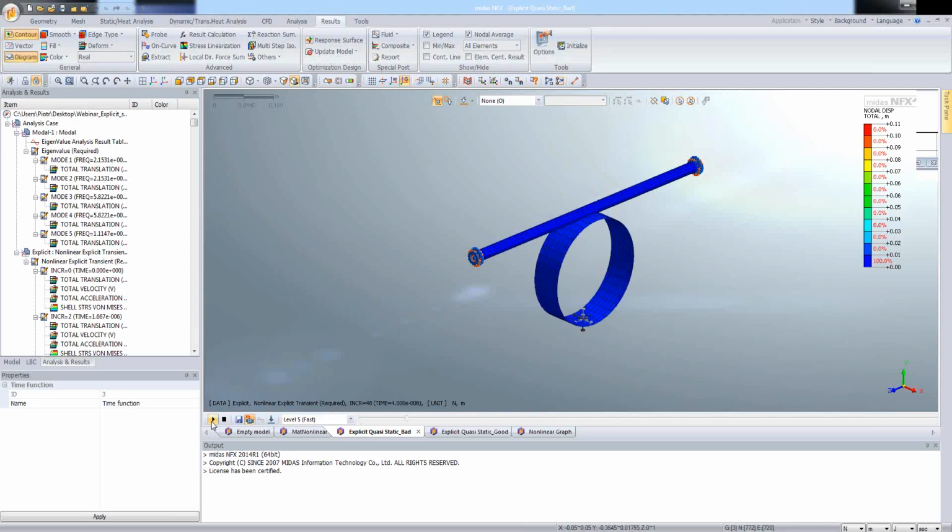Okay, so we see that there is a very deformed shape and there is no structural response as we expect for the static or, let's say, quasi-static simulation. So what we are observing is rather dynamic than quasi-static. So how to achieve the structural response? Before I show you the second model, I would like to say a few things about the loading rates, and all we have to do is to assign the proper velocity value to the system. So first of all, you have to perform modal analysis.